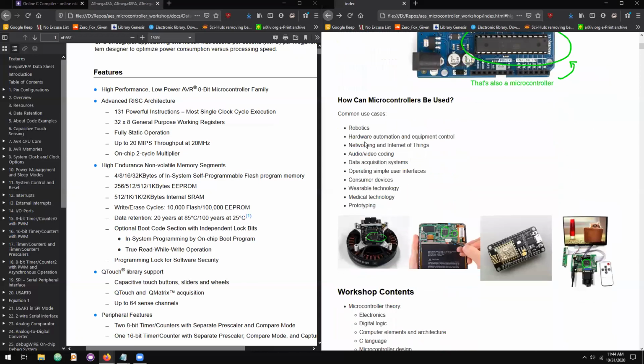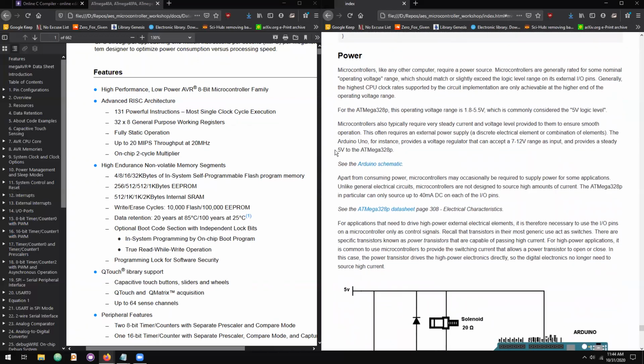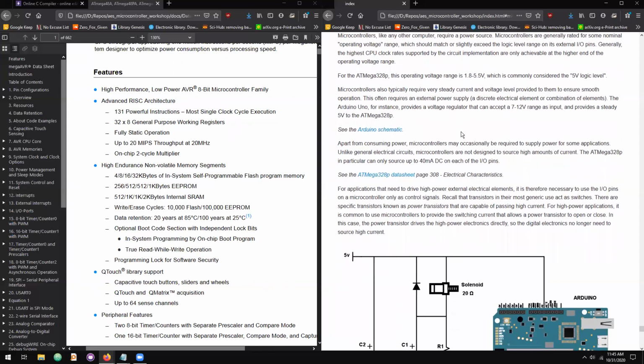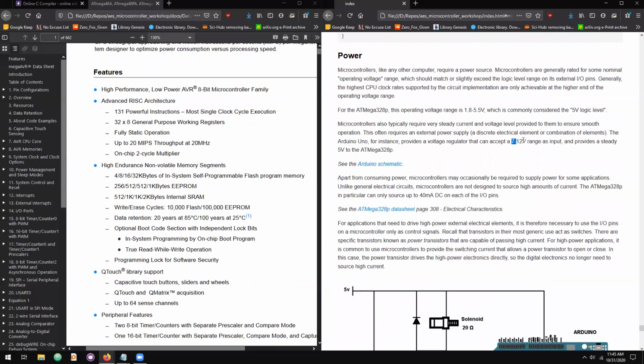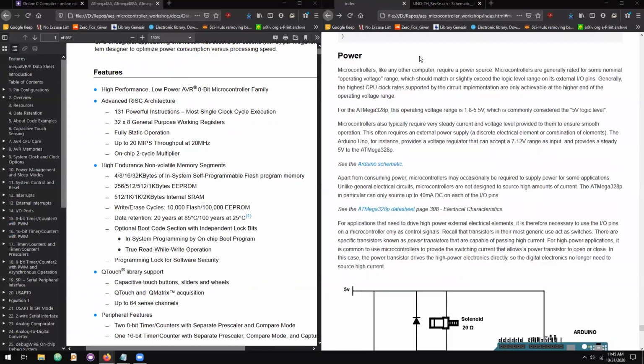So it's pretty common for microcontrollers to have their own voltage regulation for their internal hardware, but they do have to be supplied with some kind of operating voltage. And the stages for power regulation above that often depend on what kind of board you're targeting. So if Arduino Uno is our board type, then it'll also have a 7 to 12 volt power rail somewhere on that board.